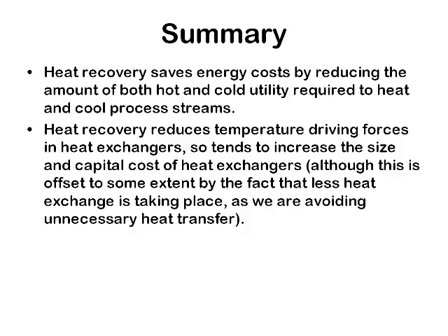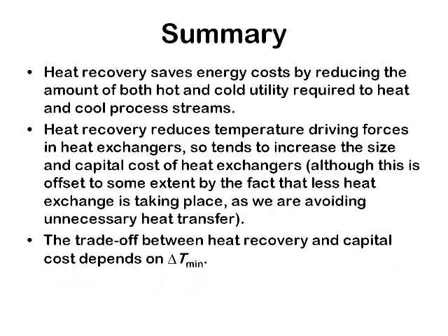So there's a bit of a balance, but in general, heat recovery reduces temperature driving forces, increases the size of heat exchangers, and can increase the number of heat exchangers that are required as well, which also increases the capital costs. So there's a trade-off between heat recovery, which saves you energy costs, and capital costs. The trade-off depends on the value of delta T min that is chosen.